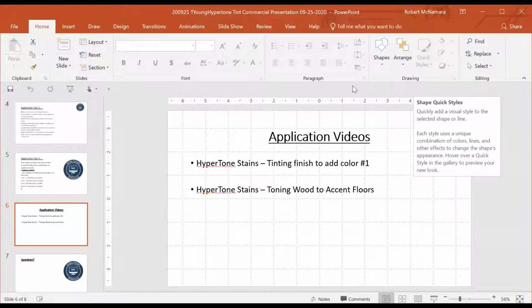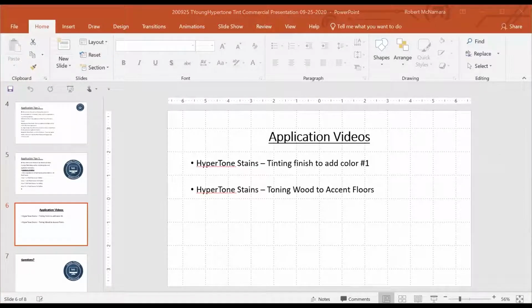The key is you want to just put it on. You want to go edge to edge on your T-bar or your pad, and you want to try and get that as even as you possibly can. That's really the only thing you're shooting for when you're applying it. You're not trying to make it smooth. You just want to make even color application. So a good indicator is just go edge to edge, pull your finish, get those lines as crisp and clean as you possibly can. Like I said before, typically on the first coat, you might have a little bit of inconsistencies in the way it's applied, but the second, and if need be, the third coats can usually tie those in and eliminate any inconsistency in color.